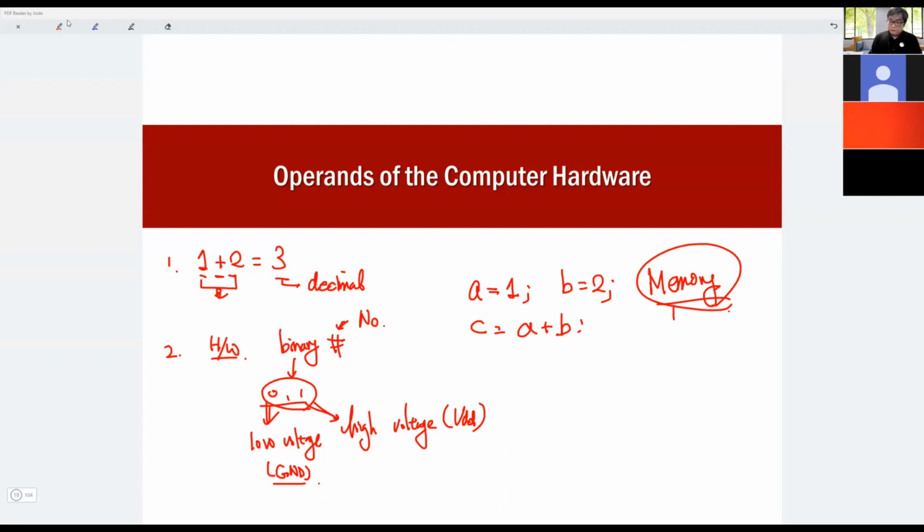First it is stored in the main memory, such as DRAM. Then when this add instruction is executed by the CPU, the RISC-V add instruction can just handle the data in register files. That means this add instruction cannot access the DRAM memory directly.